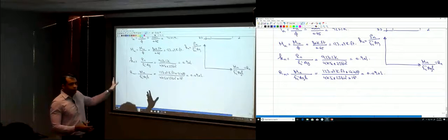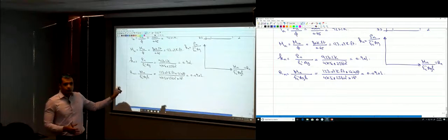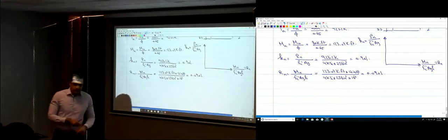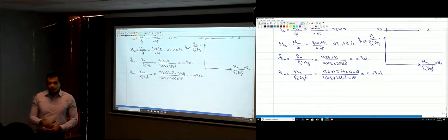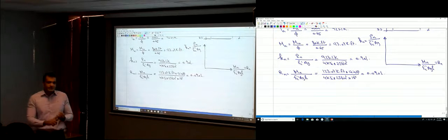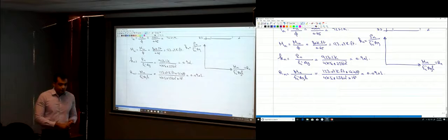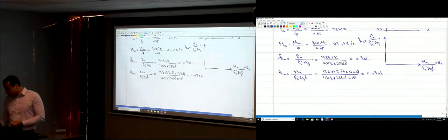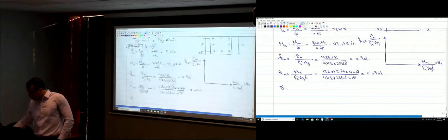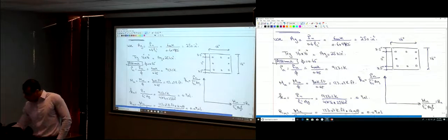So we're going to be using the 4 interaction diagrams where the steel is distributed among the 4 faces. The 4 interaction diagrams have different gammas: 0.6, 0.7, 0.8, 0.9, at the back of your book. So which gamma? I need to calculate gamma. Gamma is this 11 inches divided by the 16 inches.